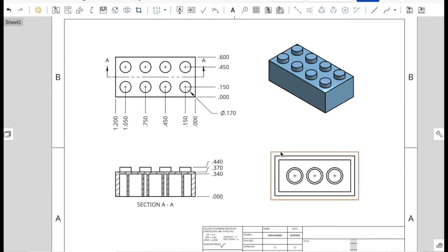Okay, let's do some Ordinate Dimension down here on these also. We'll click here and bring that up. And then we'll click here to see how thick that is. And then we'll click center, center, center. We'll click in here in the corner, and then right out there again. And yes, I know we're maybe over dimensioning a little bit. We already know that this is 1.20 across, and we're showing that again, but I think that's okay. I don't know. We'll see.